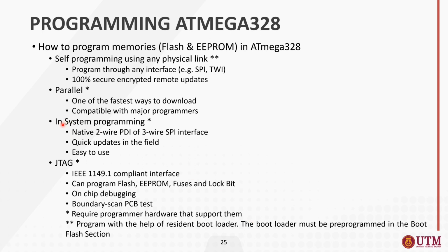And then in-system programming is actually a native 2-wire PDI or 3-wire SPI interface, and it has a quick update in the field and it is easy to use. For in-system programming, you also require programmer hardware that supports in-system programming.